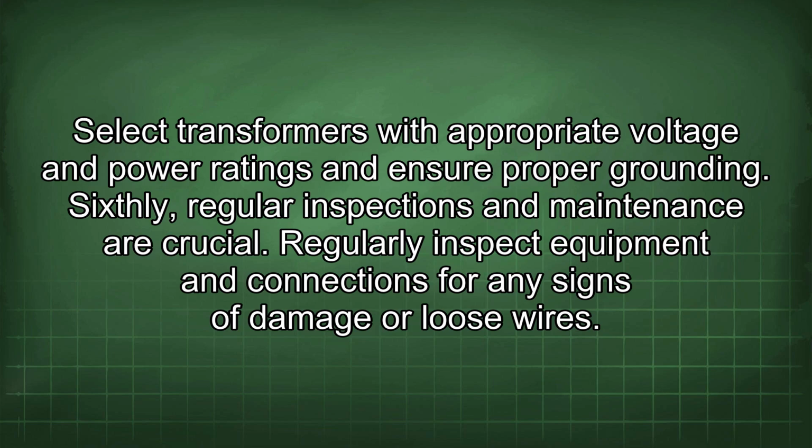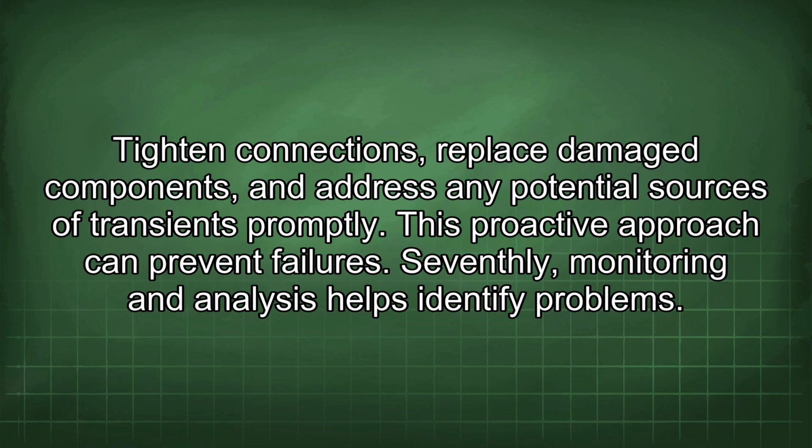Sixthly, regular inspections and maintenance are crucial. Regularly inspect equipment and connections for any signs of damage or loose wires. Tighten connections, replace damaged components, and address any potential sources of transients promptly. This proactive approach can prevent failures.